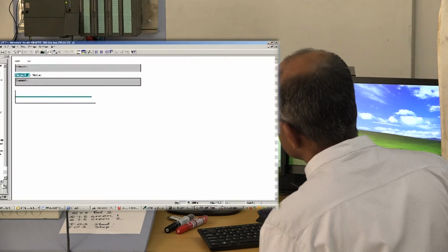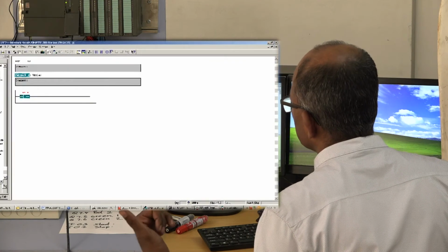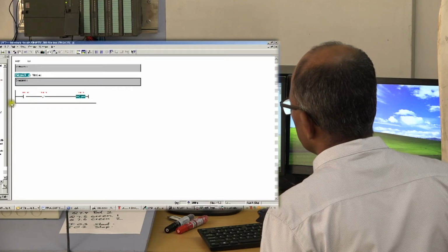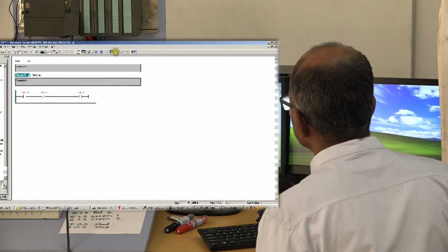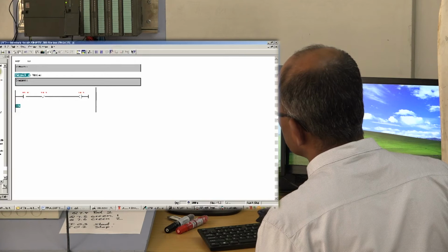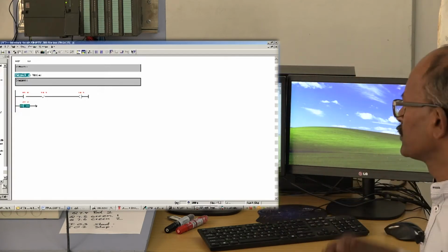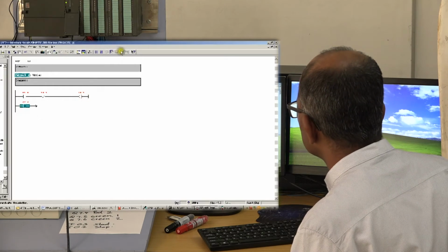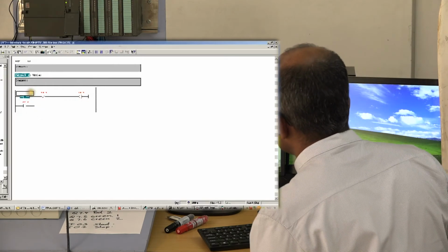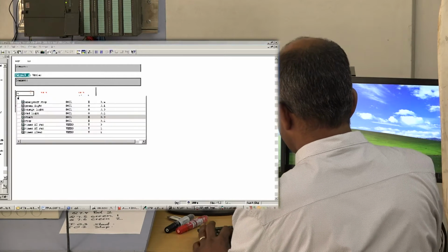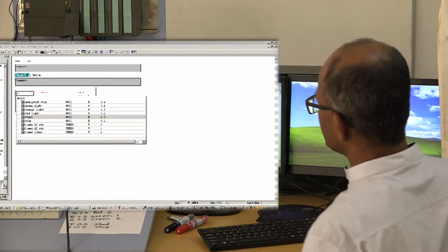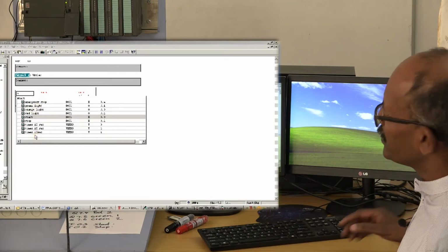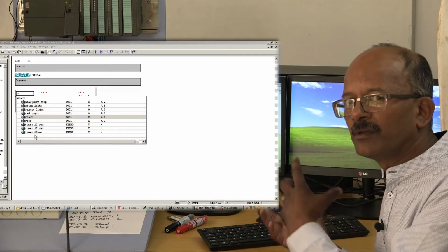Okay, bit logic, my start button, stop button, my red contactor, and remember with the red contactor, I need to add a latching circuit. So it'll be a normally open switch with the same symbolic address as my coil. For my start button, S-T-A-R-T, you can see if I just type in the word start, my symbol table comes up here, and instead of me trying to remember the address, it actually remembers it for me.